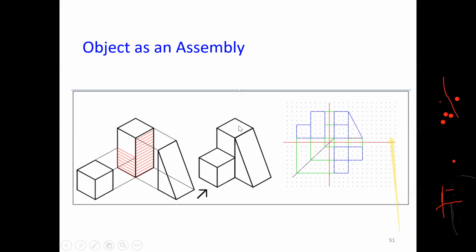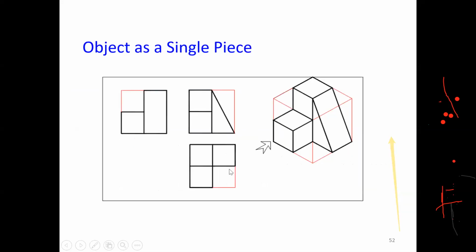If you see from the top, this square and this rectangle. This rectangle is reduced because it is inclined, and you will not get the true shape here. So only this part you have to show, and you take the projection from this corner, and then you will get the rectangle. Then for the side view, this rectangle is visible here, and then one square. Getting?